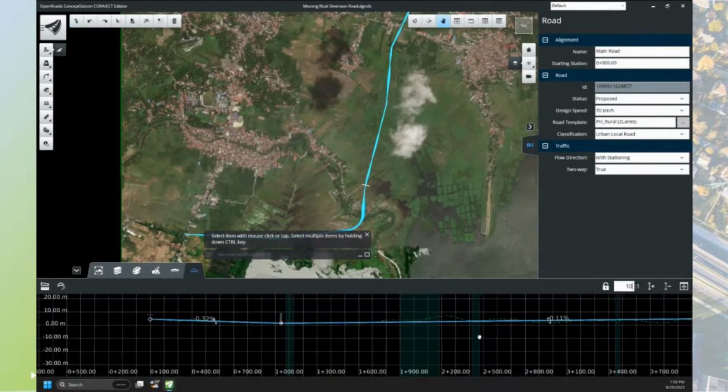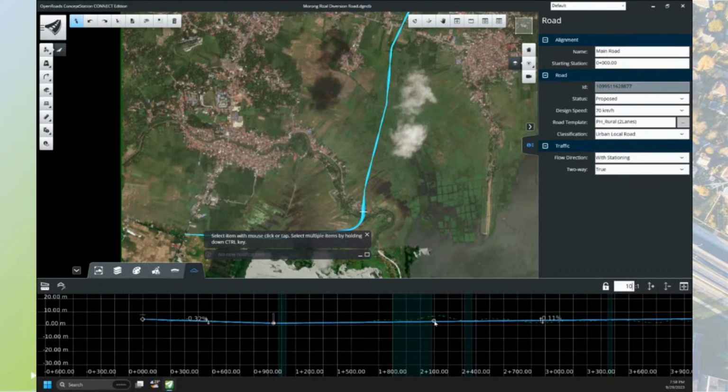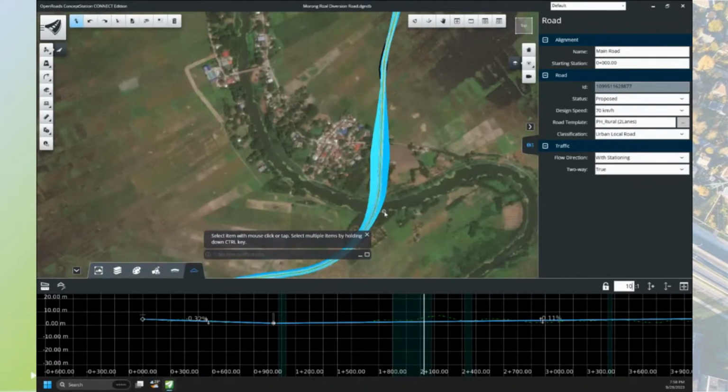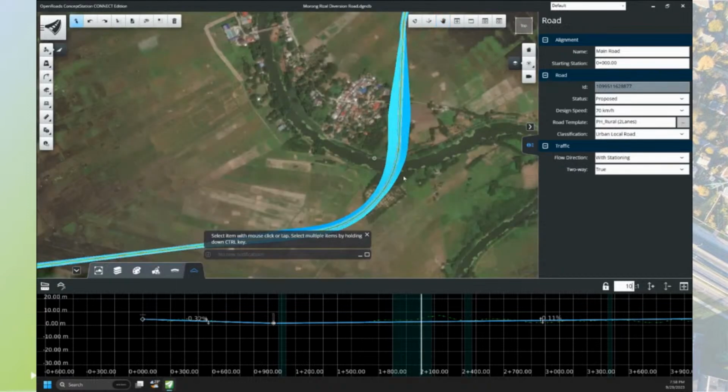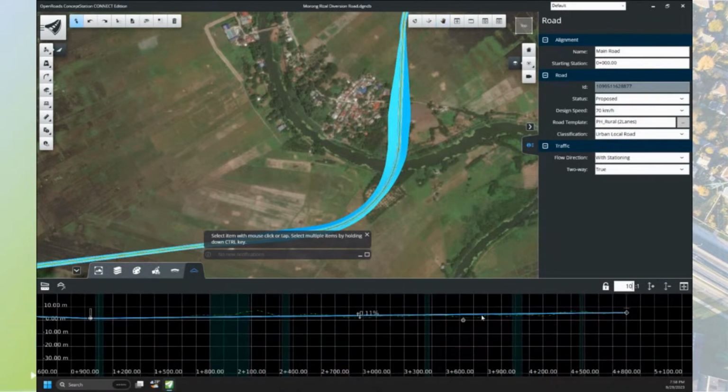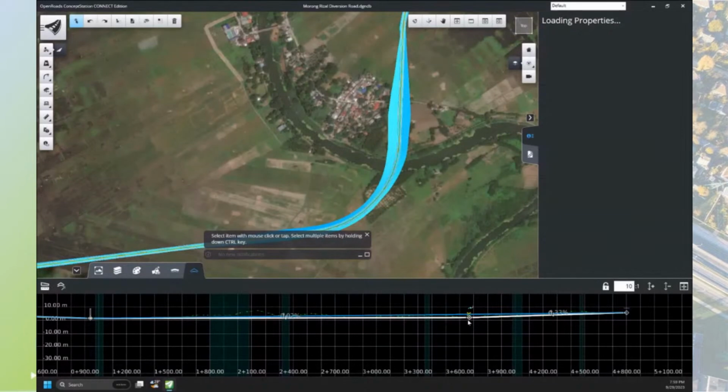And then we want to make sure that there are curves as well in our vertical profile, based on how you feel is best. Looking at this area, if you notice, we have a river, or Morong River. I think this is Morong River. So it's not applicable for us to create an upgrade type of road here. That's why later on we will add a bridge here. We'll go back to this one, but let's just focus first on the other portion of the vertical alignment.